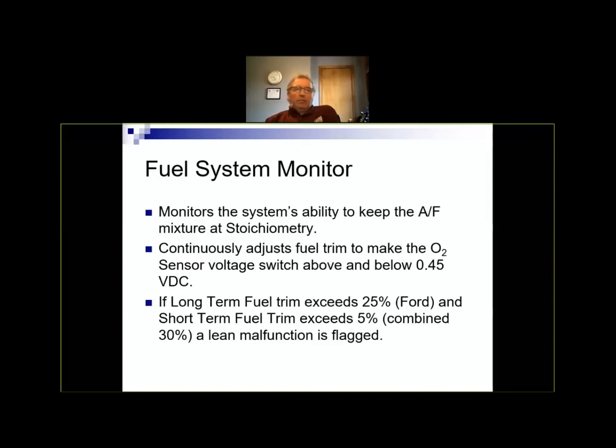Just wear and tear, the age of the vehicle. So it's just this little tweak meant to make minor adjustments in the amount of fuel delivered to keep the air fuel ratio where it belongs. So under normal operation, fuel trim numbers are very small. 2%, 5%, -3, single digits typically.